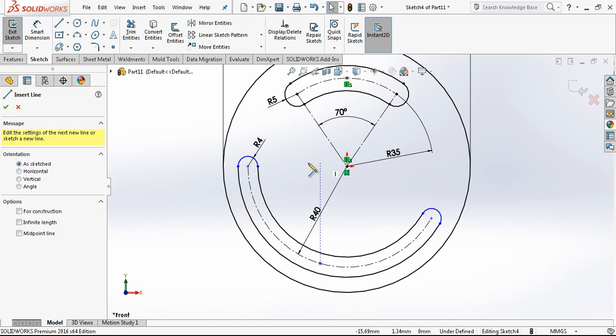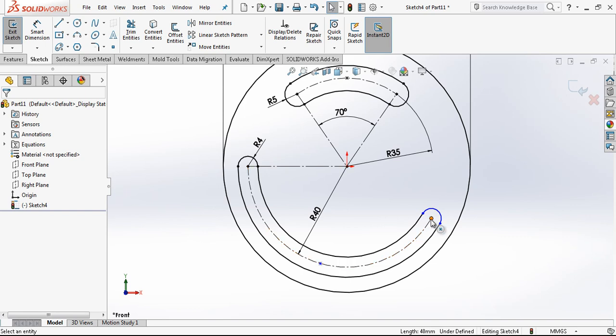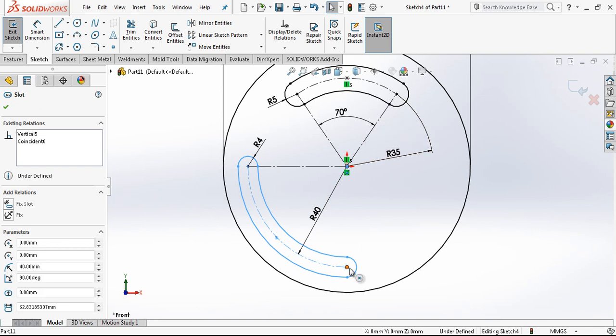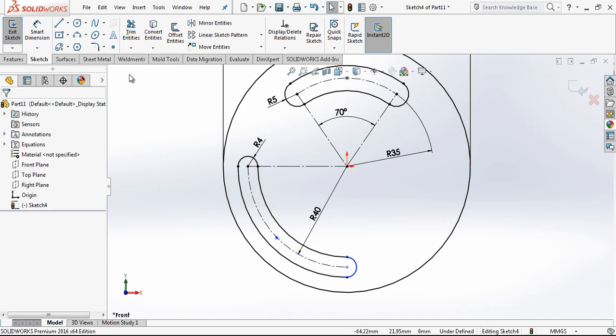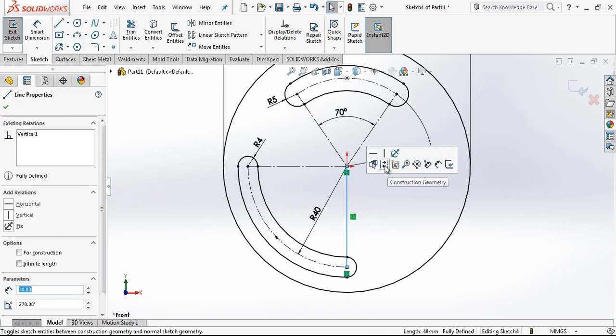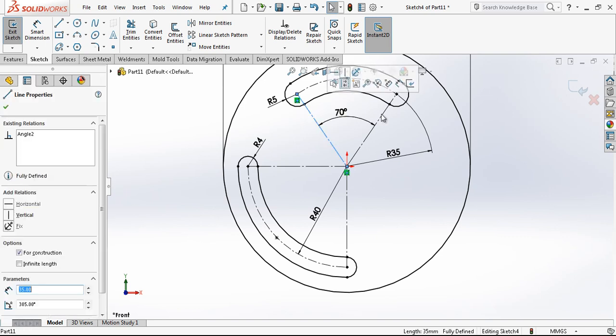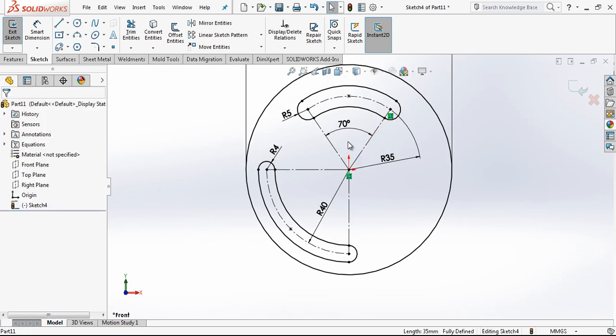Vertical, it's not there, sorry, just a line. When I draw a line from point to point, there it is. And again this point and this point I can define here with one sketch. As you see, it is now fully defined. This is in case it is 90 degrees. If it is not, then you can also use this way to give a line, and then give those helping lines some degrees, which is also going to define your model.